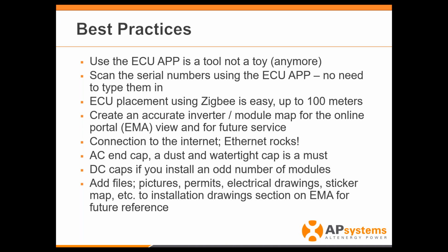And of course, for the first 2 hours of the day, they're not going to respond because they're not even installed. But like I said, once you install that first inverter and you make that first DC connection with a panel, now that ZigBee chip is energized. And now the next time that ECU asks, hey, are you there? It's going to say, hey, I'm here. So as the installer on your app, you're going to be able to see these panels light up as you're building the array. Other big advantage of that is you're building your ZigBee network as you're building the array.